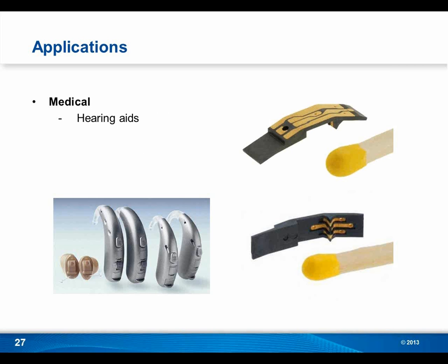Another great area of application for MIDs, and specifically LDS created MIDs, is medical. Again, reducing the weight. And what I like about this example, which is wiring and circuitry for a hearing aid, is the ergonomic shape. When you're dealing with a hearing aid, you don't have a lot of space to use. So being able to eliminate, say, a flex circuit here, and put that all on one part, you can see with the matchstick comparison just how small that part is. This part actually carries 3 microphones on it, all in that ergonomic shape, which is really cool, I think, of the 3D possibilities of MIDs.